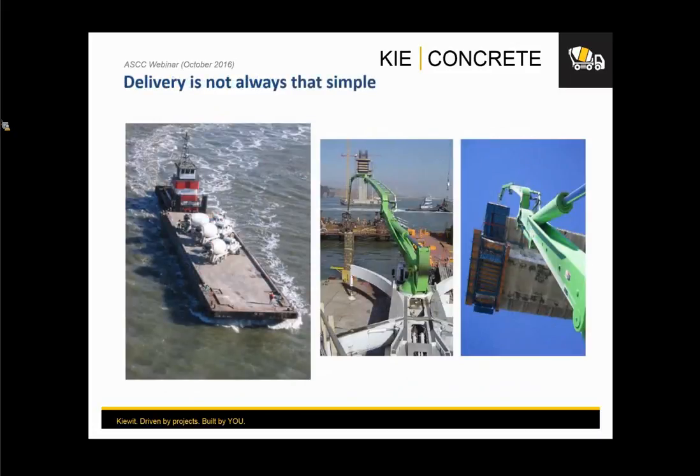The other thing to consider is that delivery is not always that simple, right? In our projects, we do a lot of bridges and mega projects, and sometimes it's not that easy, right? You need to consider, you may have to barge your trucks. You may have to pump it several times horizontally, and then you have to pump it vertically, and that's going to induce different challenges to the behavior and performance of the mix, right? So you need to make sure that you understand the demands of construction for that.